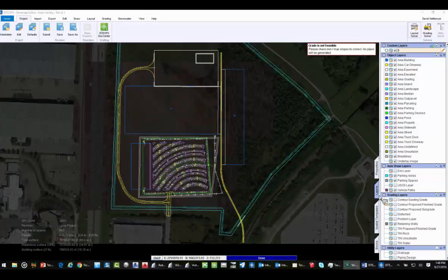All right, got another question for you here, David. Do groups of trees in geo cause incorrect topo sometimes? Again, that's going to depend on where you get it from. If you're bringing in topography into SITEOPS, and let's just say somebody went out and did a ContextCapture. ContextCapture, for those who might not know, is one of the drone processing tools that will look at your photography and create a 3D model. Now, if you do not go in, I believe it's Descartes, that helps edit that surface, and it has those trees, and you bring that model into SITEOPS, it's going to look at the tree and say, hey, I've got a big mound of dirt right in the middle of my project, because it doesn't understand that surface is trees.